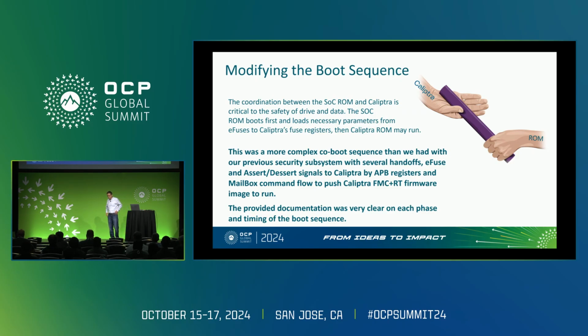For the boot up sequence, I'm a hardware engineer, so I'm not very familiar with it, but we have a Caliptra firmware and also our in-house firmware. We boot up, co-working with the Caliptra firmware, and boot up our firmware through the bootloader, BL1, BL2, BL3. The good news is that in the first 2 days, I think, we already successfully booted up the Caliptra ROM code without any problem.